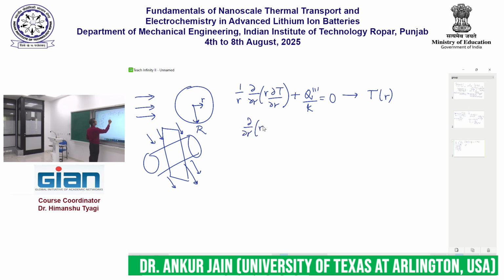d/dr of r dT/dr equals negative q triple prime r over k, right? So if I integrate it once, I get r dT/dr equals negative q triple prime r squared by 2k plus c1.